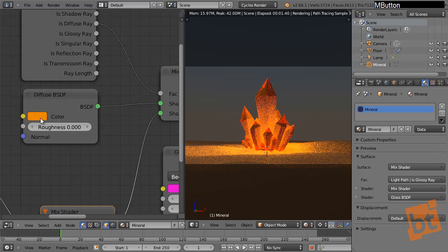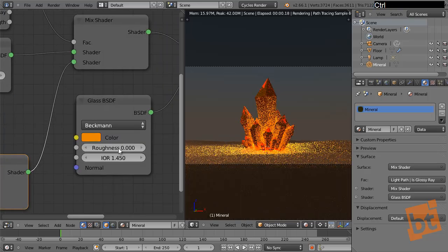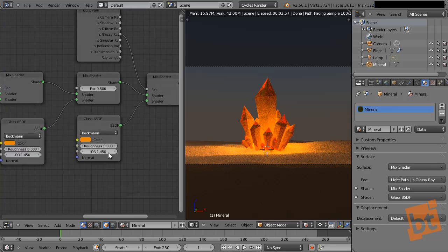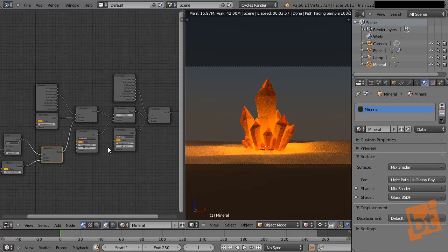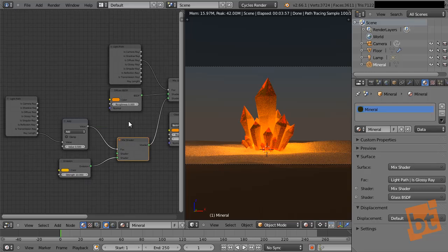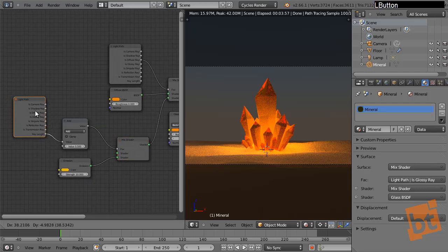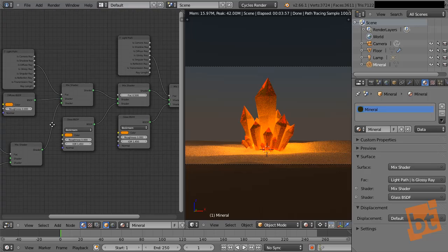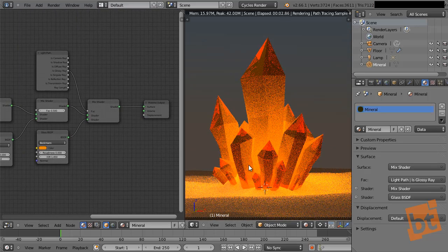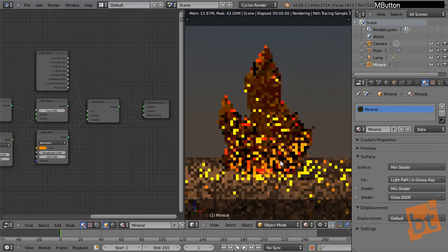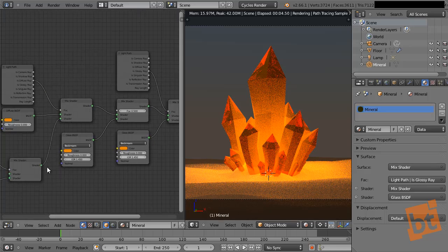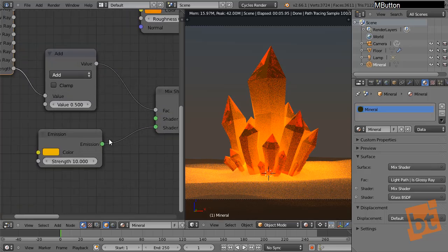And let's actually copy this color with Control C, Control V, and Control V. And we could play with the index of refraction, the roughness, or everything, but I don't want to make this tutorial very, very long, right? Because I think that you already learned something about the great potential of the Cycles materials. They allow us to create very interesting effects like these ones, and we can keep playing with them as long as we want to create exactly what we need or what we like, right?